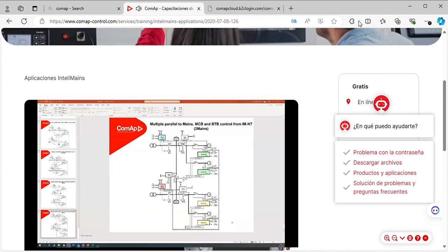let's go to auto and let's go to auto here as well. And even this one at auto. So now everything is in auto mode, but you see the genset tripped because this controller was not in auto mode. And I'll set it to auto here as well. Now all the systems are starting again. They will try to synchronize and take care of the load.